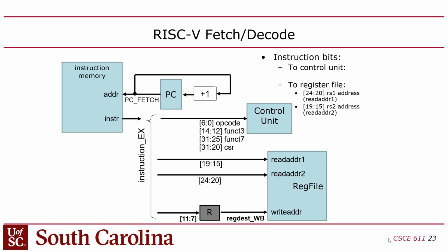The problem is when you add a module, you have to create a new file, put the stuff in the file, then figure out what the names are in the module versus the names of the things coming in. Then you have to put the module in and wire it up, and if I don't have to, I don't do it because it's too much work when I can just stick an always_comb in and have the code.